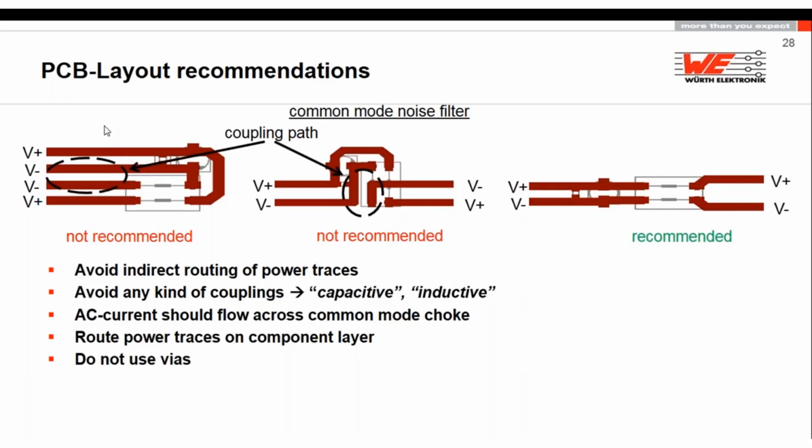You have the noisy area on this pad. You try to filter it, you put a common mode choke, but after the common mode choke, in the filtered area, you couple back the noise. If I would not see it with my own eyes, that this is so important, I would not believe it.